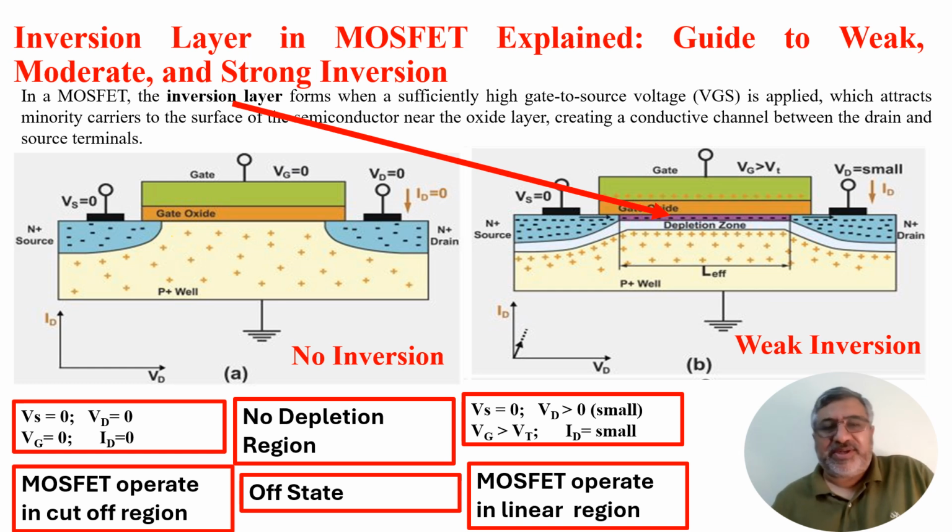as non-conducting states. Initially, the MOSFET substrate, typically P-type for an NMOS semiconductor field effect transistor, has an abundance of majority carriers, which are holes, and very few minority carriers, as electrons. When a positive voltage is applied to the gate in case of NMOS, the electric field generates across the thin insulating oxide layer, pushing the majority carrier holes away from the surface of the p-type substrate and creating a depletion layer, like that here, where the carrier concentration is very low.